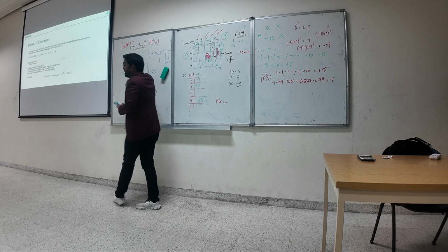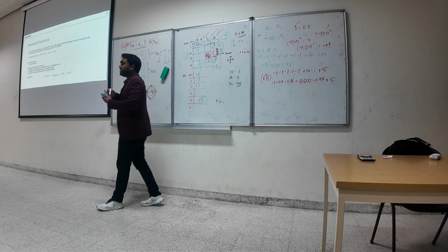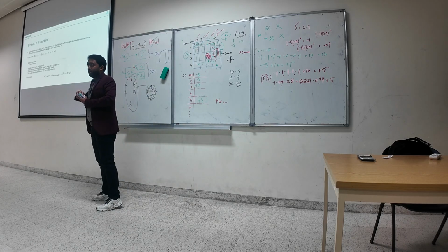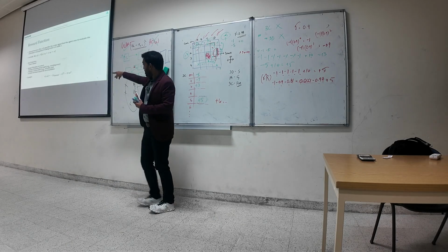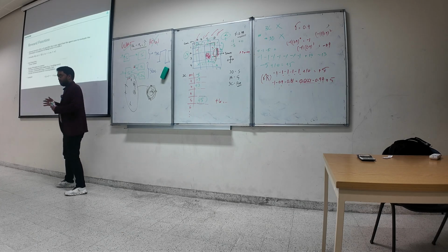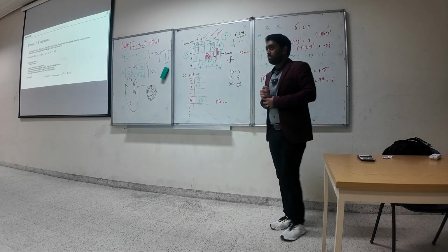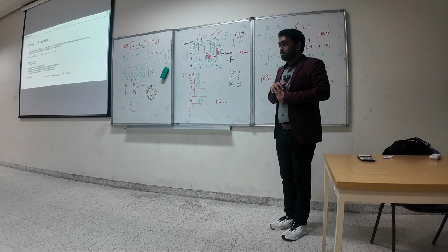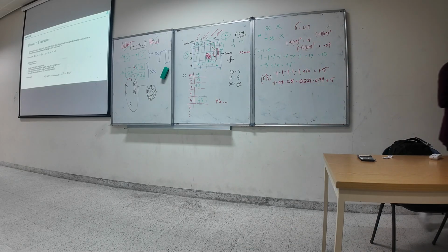So this will penalize the change of actions. That means there is no rapid change of actions. Here it will simply ensure that the thrusts are not very high. For example, if action is a thrust, thrusts are not very high, because say a higher value here, squared, will give you a very high negative reward, which is a penalty basically. Instead of putting a thrust limit change, for example. Yes, instead of a thrust limit change. Okay? Clear until this point?